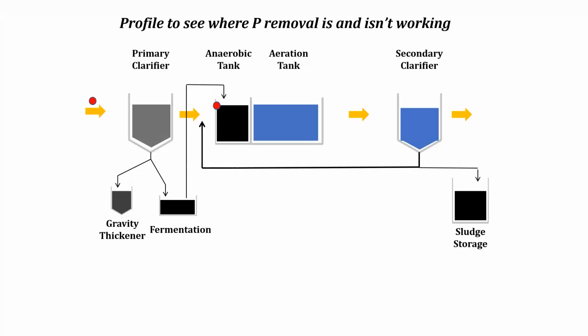That's the part that we as operators manage, is trying to get that phosphorus out of solution into the mixed liquor, either chemically, like Nick talked about at the opening, or biologically. It's still in the mixed liquor. If it's in the mixed liquor chemically, it's in there a little better, a little stronger. It's more resistant to being re-released.